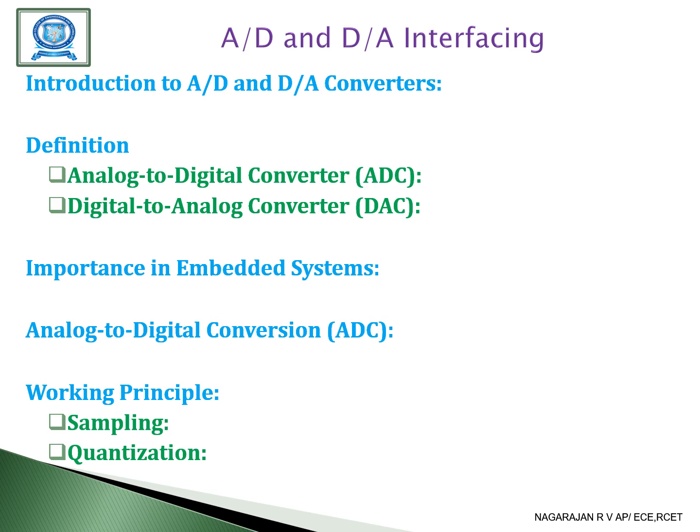For example, 8-bit, 10-bit, 12-bit ADC. Higher resolution provides a more accurate representation of the analog signal. Next one is encoding. The quantized value is encoded into a binary format that the microcontroller can process. So this is the basic working principle behind the analog to digital converter. First is sampling, then quantization, and after that encoding.